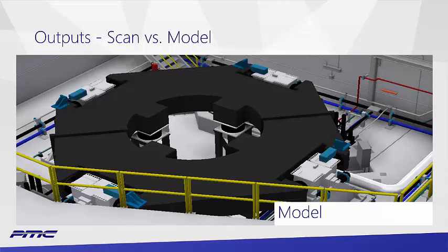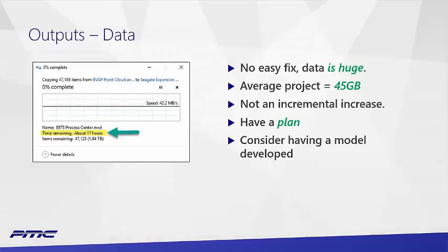One thing, and we're going to touch more on this as we continue through here, point cloud data is big, and for anyone who's not used to working with it, before you get into it, you should have some kind of plan for dealing with that. If it's your very first time working with point clouds, consider having someone develop a CAD model for you. That's going to be a lot easier to work with for your first project or projects than working with the point cloud natively.